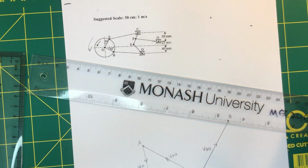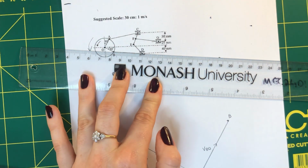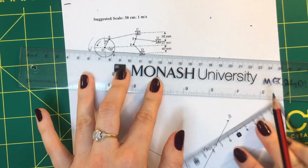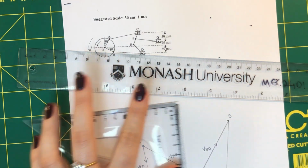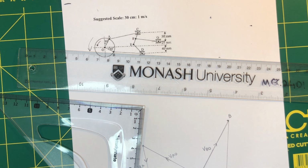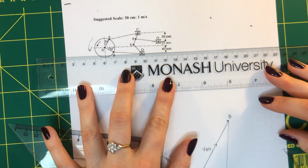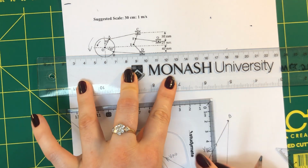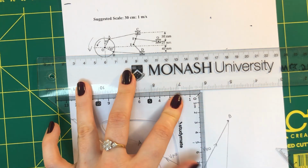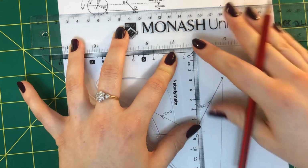Here we have velocity of D relative to B: ruler along the link, set square along the ruler, drawing the line. Now we don't know the length just as before, but we do know the location. And then we have another slider, so our ruler along the line of the direction of motion, and then we put our first set square in. Let's see if I can do this.